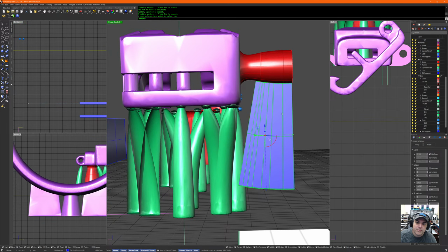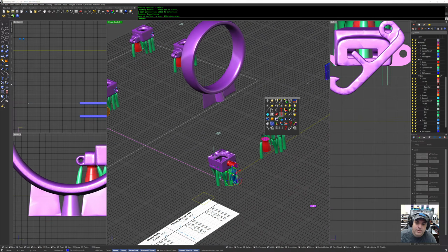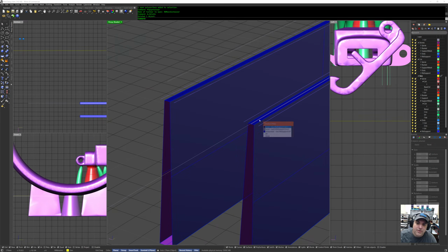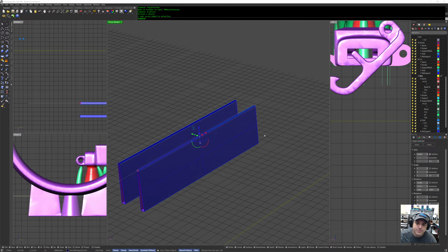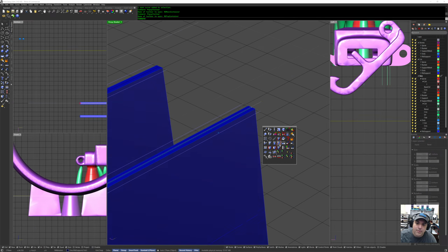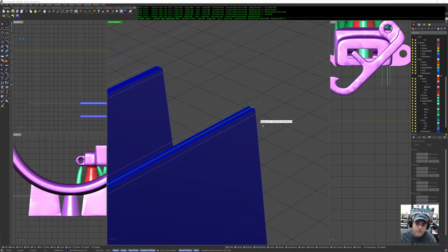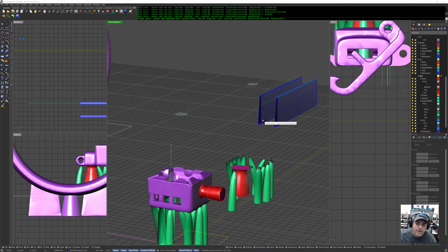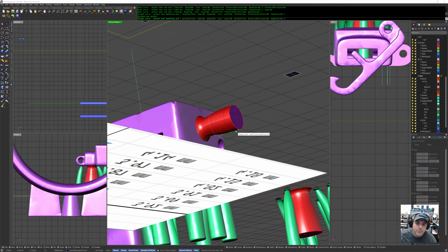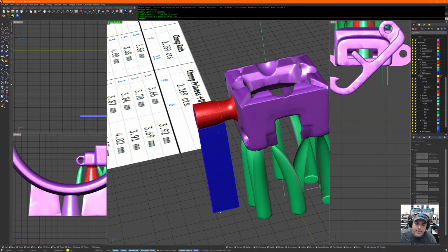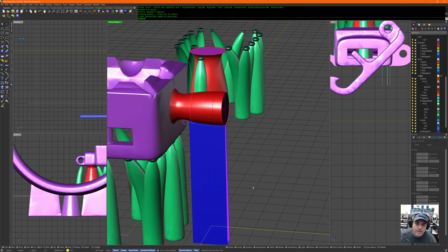That's about where I want that rib to go. Okay, so now I'm going to delete that. And now I'm going to take that curve that has all the history on it, and I'm going to say flow stretch without copy. So it's going to move this curve from here to there. And when I move that curve, it's going to move all the history, which includes a project to C plane. And that gives me this.